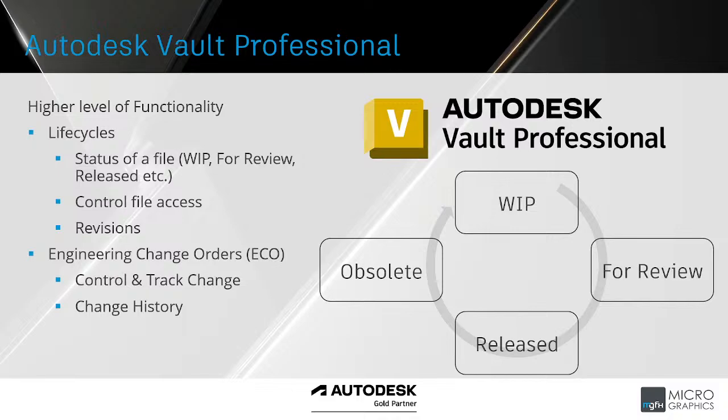So if it's in work in progress, manufacturing cannot access that file. Manufacturing users cannot see it or use it because it is still work in progress. If it's for review, the design is locked down until it is approved and released for manufacturing. Even when it's released, it will be locked for changes so that it cannot be changed while being manufactured. And if change is needed, then Vault has the ability to create and track engineering change orders.